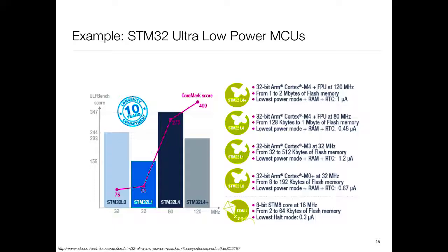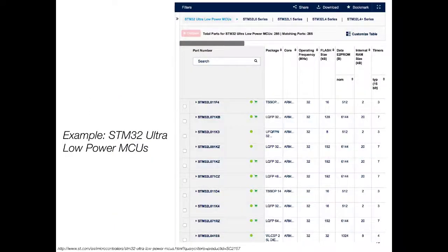One thing to also notice is that memory is extremely power hungry, because the moment you have static RAM, its state needs to be maintained, and that burns power. So selecting an MCU which has an excessive amount of memory has a persistent cost, not just dollar cost, but power cost also. So choices matter. And I just wanted to show, lifted from their website, that even in those ultra low power MCUs, they provide a whole family of choices.